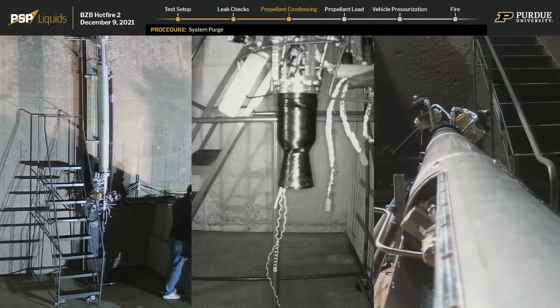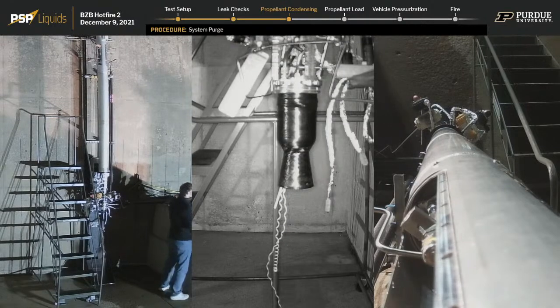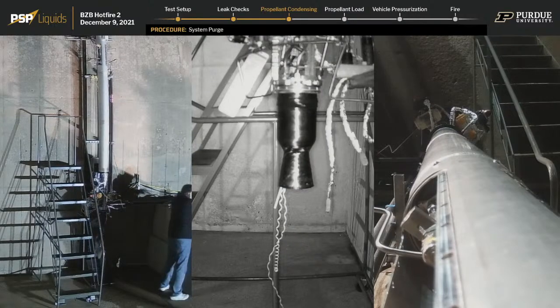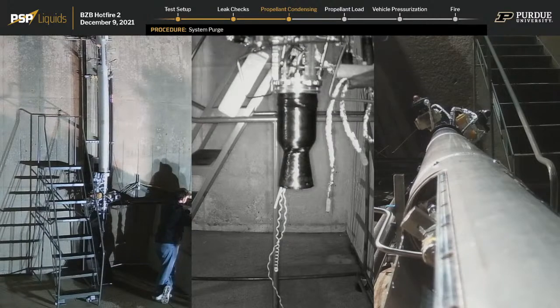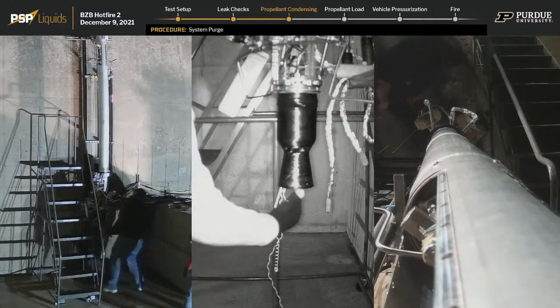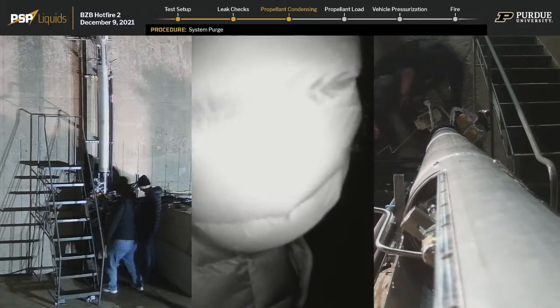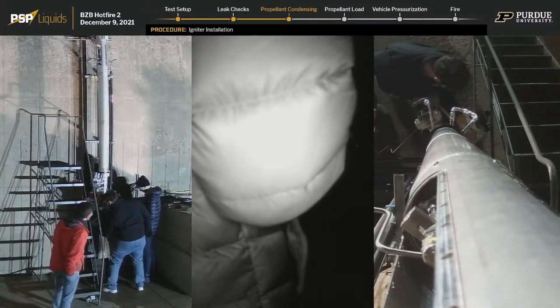Right. And can you talk about what happens when a rocket engine is ignited? When the rocket engine is ignited, you have your valves actuate and propellant will flow into the injector at a high pressure. Then our injector, what is known as a pintle injector, will inject the liquid methane and liquid oxygen in a spray, and these sprays will mix, and then the solid propellant will ignite this mix.